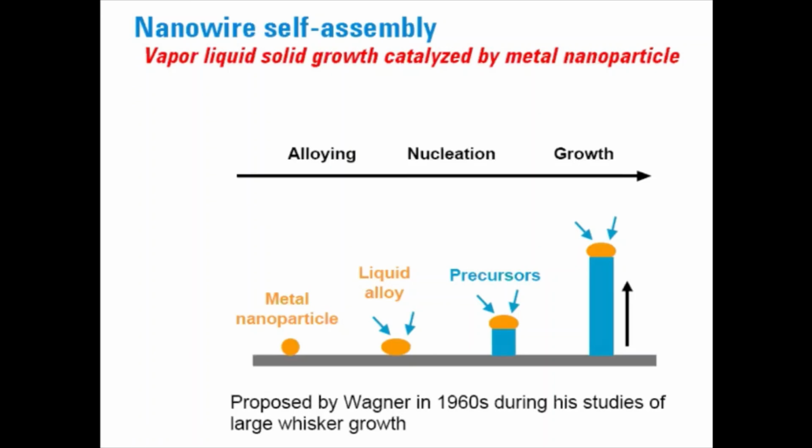the issue is that silicon and gold mix in the liquid state, whereas they do not mix in the solid state. So if you choose a suitable composition of this eutectic system, when you cool, the gold melting point is less than the melting point of silicon. So gold liquid is formed, and in that liquid the silicon gets dissolved, and from the vapor the growth keeps on going, the liquid becomes solid, and on top of it, the silicon liquid layer is retained.